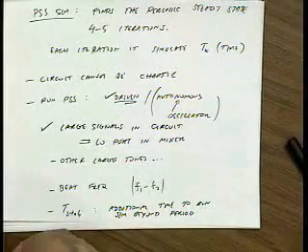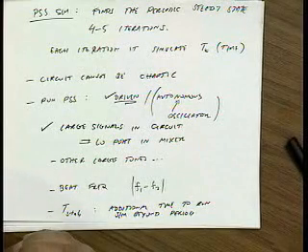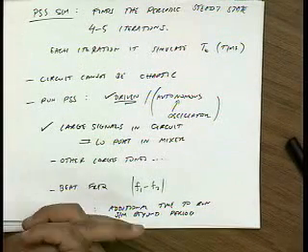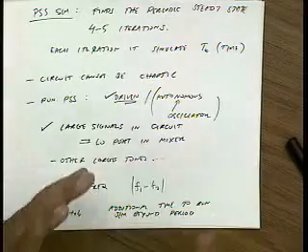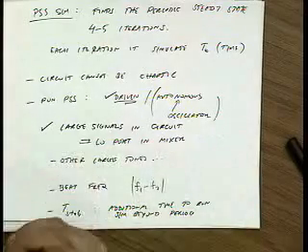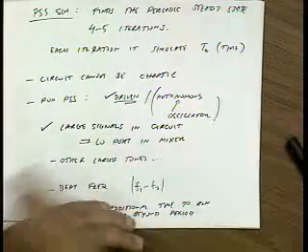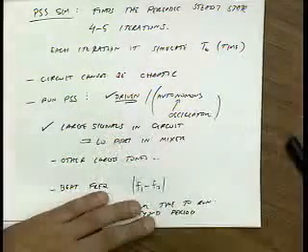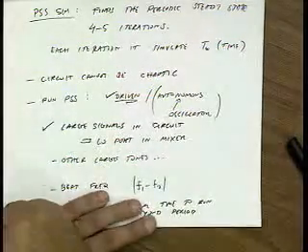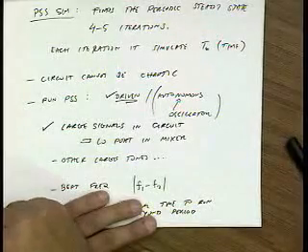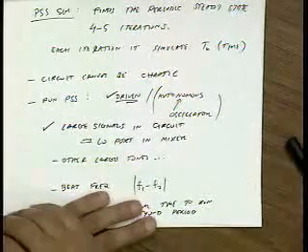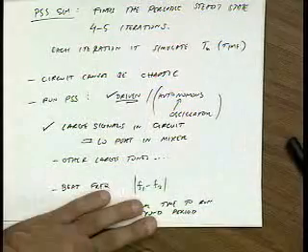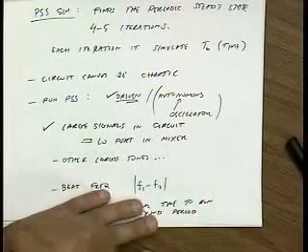Because, for instance, let's say I have just R's and C's in my circuit, critically damped. A few cycles, boom, the transients died off, right? Let's say I have lots of poles in the left half plane, and they all have very short decay times, so they all decay away, and I get to periodic steady state. Other circuits, though, let's say high Q circuits, take a long time to reach periodic steady state. So let's look at a high Q circuit.